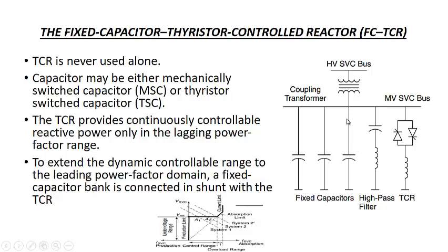So we assume that the current drawn by the capacitor is IC and this is IL. This IL, at the protection limit at alpha equal to 90 degrees with respect to peak, should be more as compared to IC, so that when we add them, since they are reactive currents, the total current will be equal to this current minus this current.